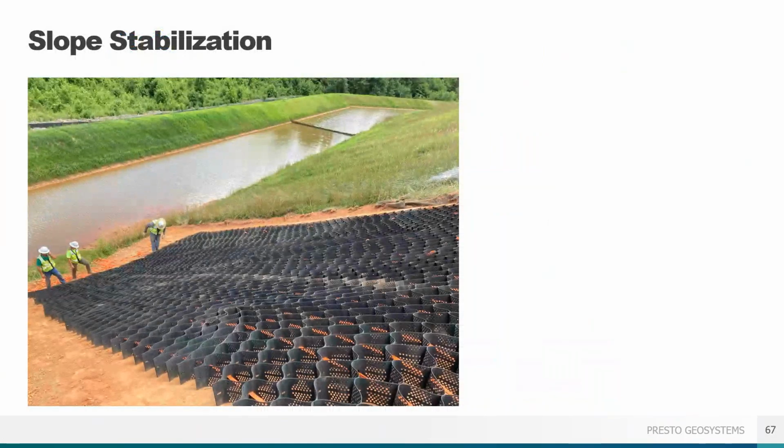Okay, back to slope stabilization and pre-assembly. The pre-assembled sections, once connected to whichever version you have of the crest anchorage, are then hung over the slope like a curtain and extended down slope. Again, a best practice or great technique tip is to do all that pre-assembly on the flat or crest of the slope. It's much safer, quicker, and easier.